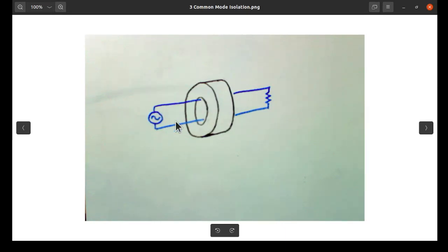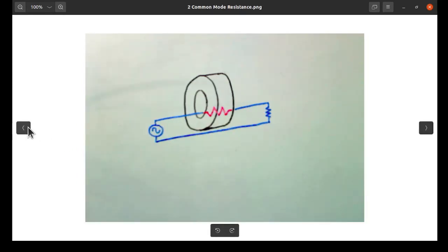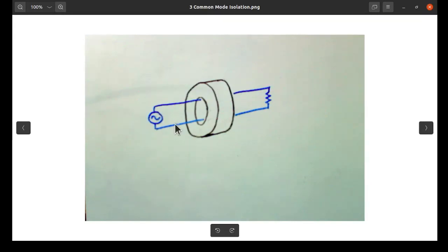And this source, through this transmission line, is connected to this load. We have absolutely no resistance presented to this loop. Now notice that this loop is entirely going through the middle of the bead. This is significantly different from this situation. Notice that I have a resistor introduced by virtue of this being unbalanced. This is unbalanced. This is balanced.